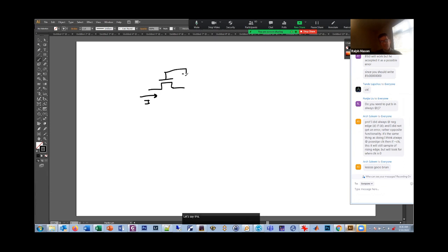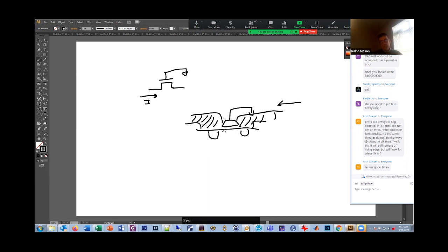So think about it. Let's say this is an NMOS transistor and this is turned off, okay? So normally we have our transistor here. This is tied to ground. So this is open, right? But also remember that this is filled with metal, okay? This is metal that connects on one side, and likewise, there's metal that connects on the other side. If you put enough current through here, you can heat this whole thing up, and the metal will penetrate underneath here, and it'll make a connection.